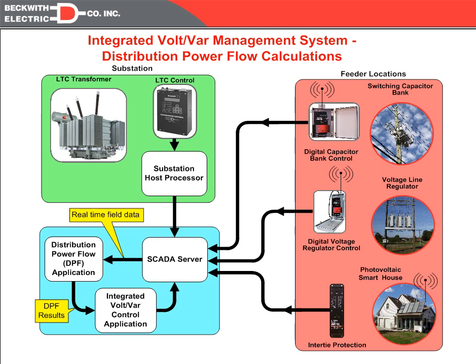And depending on the complexity of the system, there may be only one component or two components. For the more complex DMS and SCADA Masters, they may run a real-time load flow analysis and then have the output of that load flow analysis go into the volt var application. Typically substation approaches will not have the load flow, and a lot of the SCADA systems may not have the load flow.